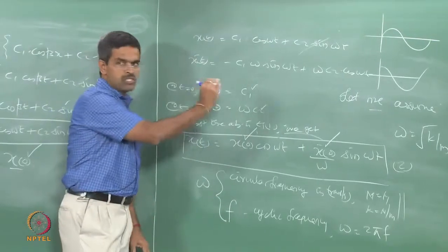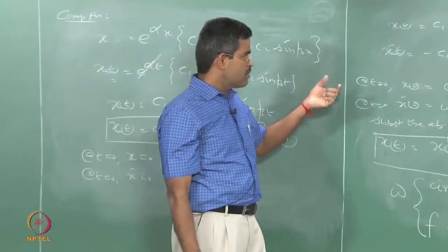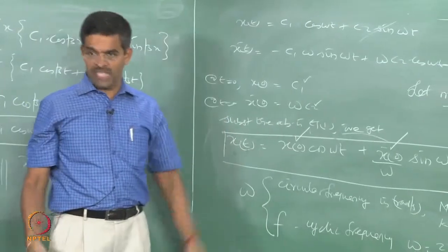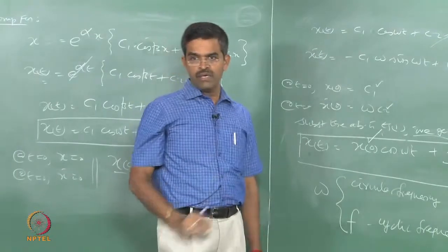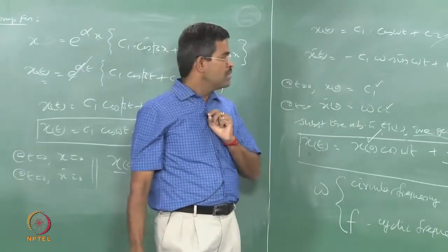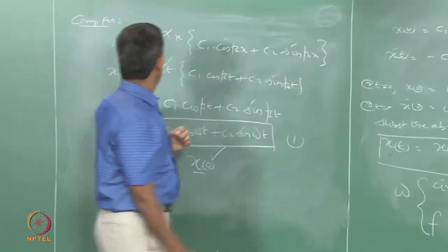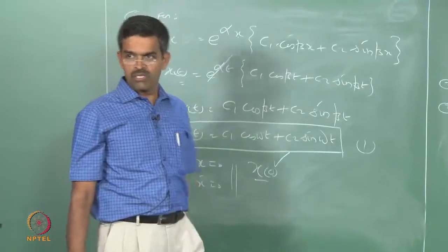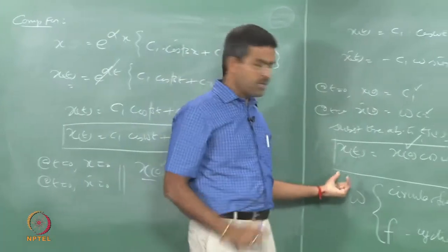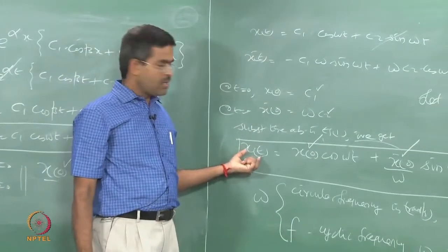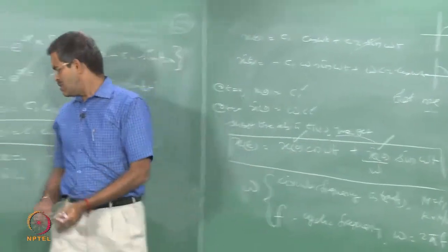So, by writing the equation of motion in simple harmonic or in any other method, we got an equation of motion, which is fortunately for us an ordinary differential equation of second order, because the variable of the highest order is 2, in this case d square y by dt square. So, second order. I have used complementary function and particular integral. In this case the particular integral is 0, because the right hand side function of this equation of motion is 0. So, there is no particular integral for the solution; I have only one answer, which is the complementary function, x of t, where there are two constants. I determined both the constants from the initial conditions which I have assumed here.